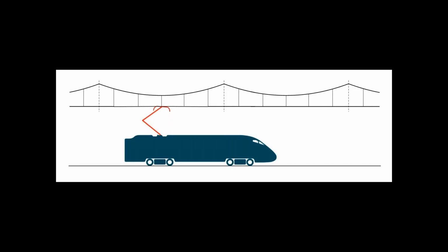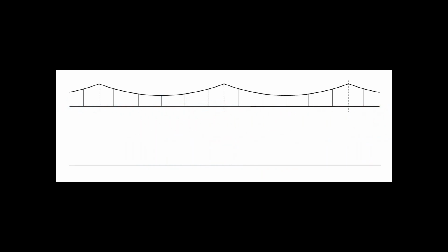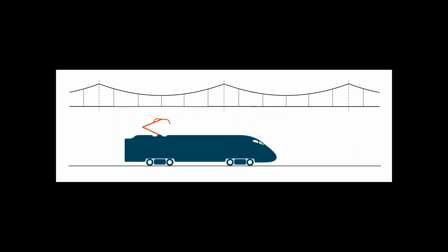The problem is, as soon as the train begins moving, the force takes on an aerodynamic component, which is much harder to control. And at high speeds, above around 80 miles an hour, the aerodynamic component dominates the behavior of the pantograph. Now, good current collection is achieved with a contact force broadly between 0 newtons and 250 newtons. If we go below 0, we lose contact with the wire, and we've seen that that's bad. If we go above 250, we start increasing the wear on the wire. We go above 350, and you're getting into the zone where you run the risk of damage to the OLE.